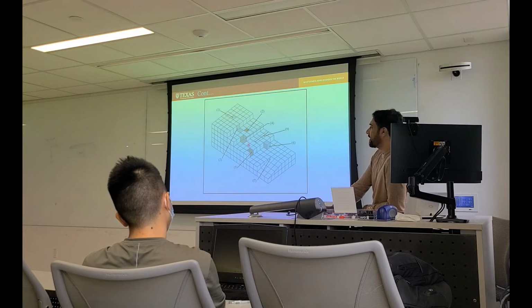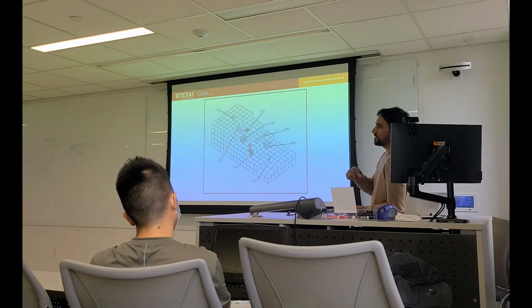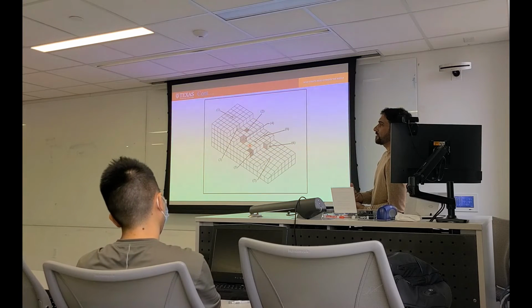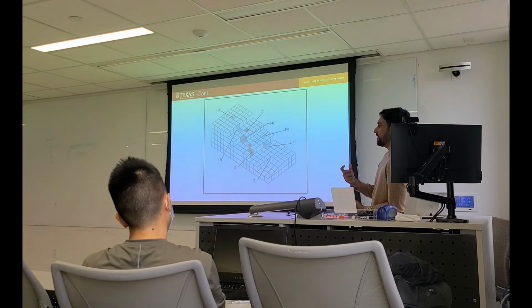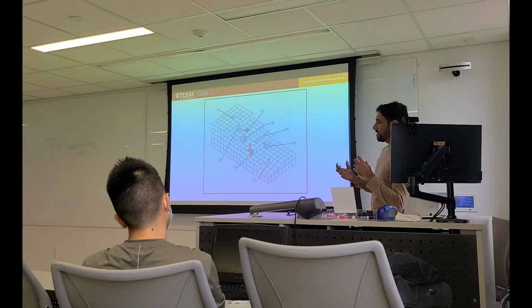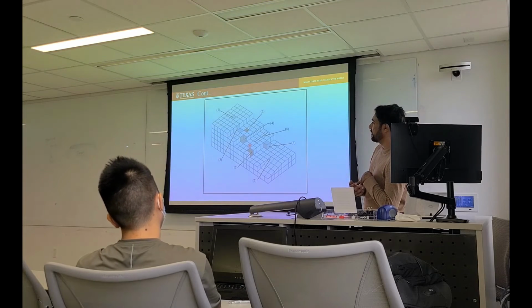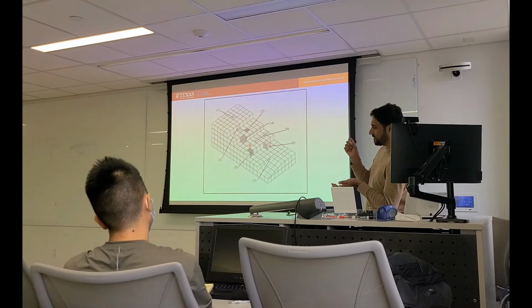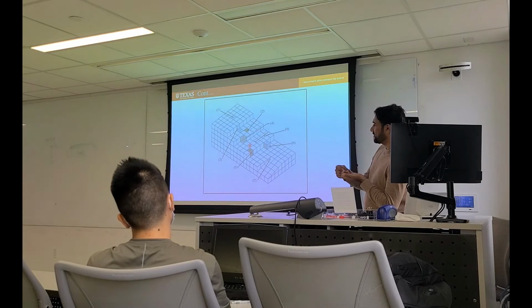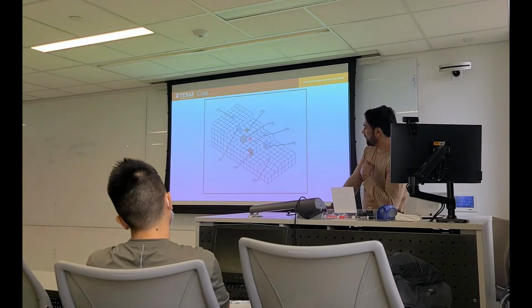Okay, so your adatoms, when I talk about adatoms, means your growth precursors on the substrate. Like you are using trimethyl gallium, its pyrolysis process is that it dissociates into dimethyl gallium, then monomethyl gallium. The activation energy of monomethyl gallium is very high. It directly goes on the substrate and it breaks during the diffusion process. Suppose it does not break during the diffusion process, then you will have carbon contamination in your crystal.